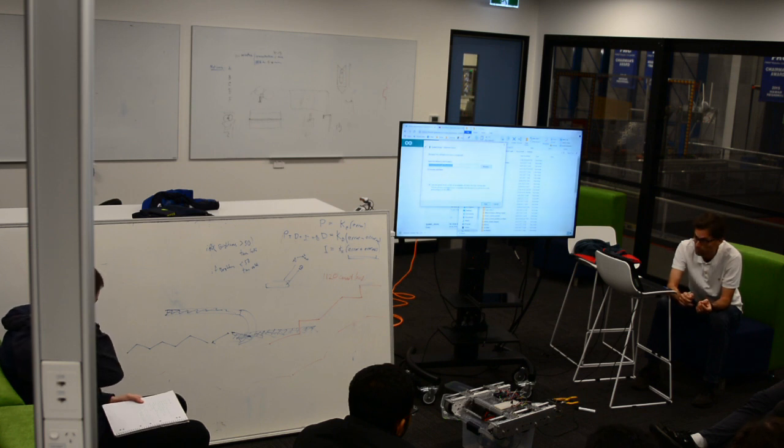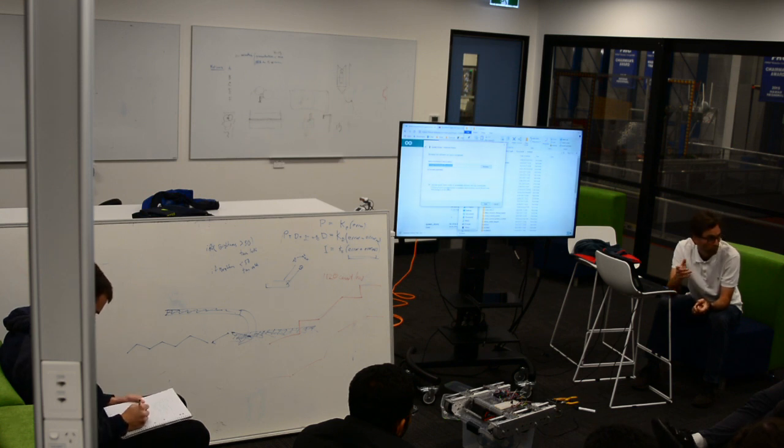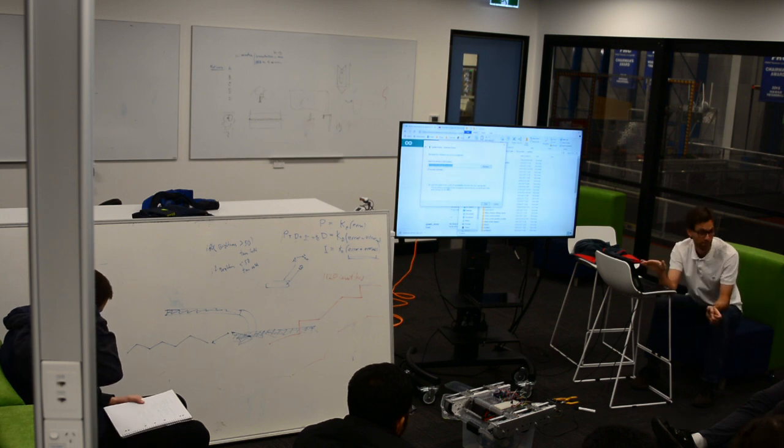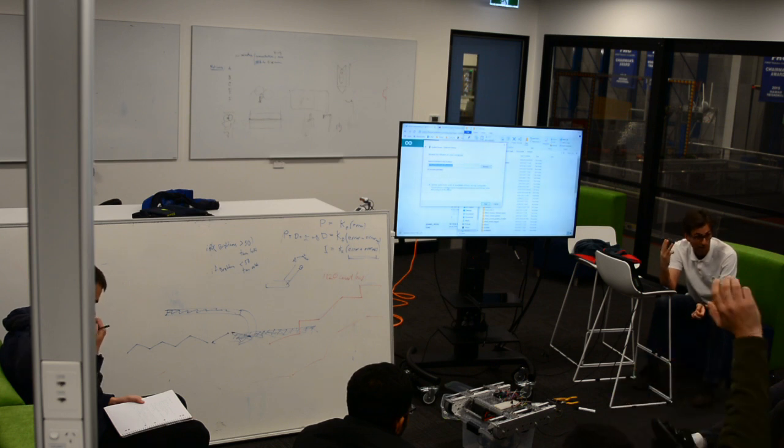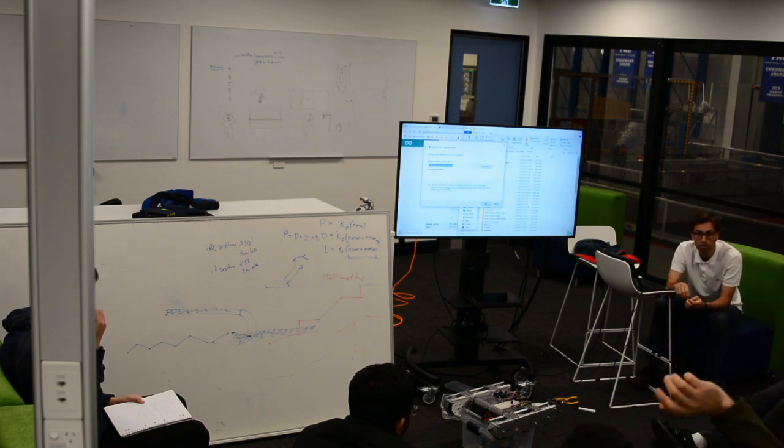But if you're going to use the PID library, look up and read about a PID tuning protocol. There are protocols for tuning PIDs. PIDs represent 90% of all the controllers in the world, and there are plenty of people who know how to tune them, and there are procedures where you turn this until this, and then you turn this until this, and then you're done, right? If you don't follow that procedure, you've got 3 parameters and a large parameter space to explore, and you will be there for hours.